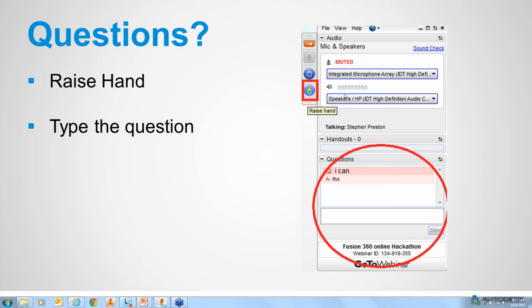Or I could draw a line that's at a slight angle to another line, and then revolve that around the line, and that would result in a cone too. So there's a lot of ways I can end up with a cone, but there's just not a primitive command to create just a cone all by itself.